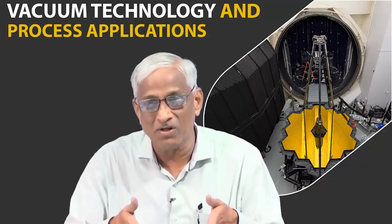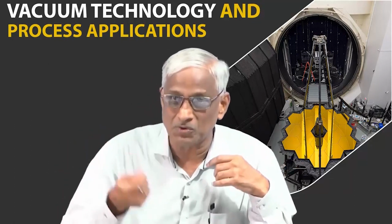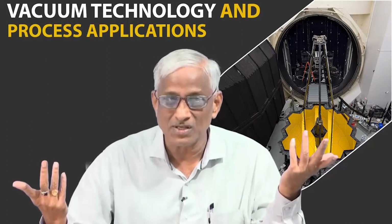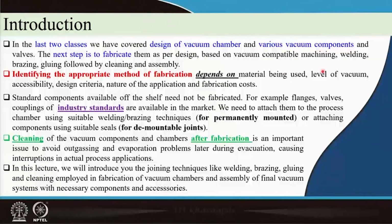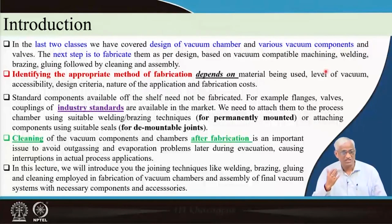So, while doing all these fabrication issues, you have to keep track of internal leaks, external leaks, flanges, and how they are going to couple. If you just make a bad weld, then it is of no use, even if you have very costly pumps. So, we have to identify the appropriate fabrication method, and it depends on the level of vacuum that we are dealing with. If it is a high vacuum, one style; if it is ultra high vacuum, another style.